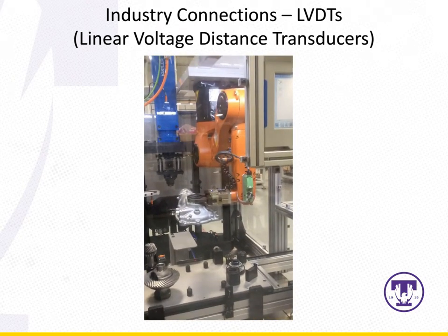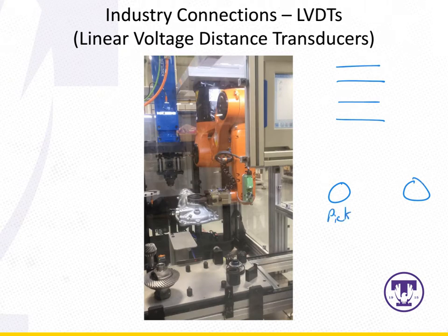So notice, you might be thinking, well, why couldn't we use a bit latch sequence for that? Well, you could, potentially, but it's not actually a great fit because it's not a simple progression of here's the order of operations, 1, 2, 3, 4. It's we want to pick shim and we want to place shim. But the only way to go from pick to place is if we get the signal shim correct.